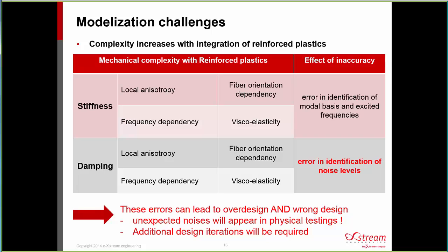It means that locally you've got a damping behavior which is anisotropic and dependent on the fiber orientation. And the damping is also highly frequency dependent, perhaps even more than stiffness. All of this is rarely taken into account today, at least the anisotropy and the link to fiber orientation for damping is really never taken into account, because there is nothing to do it.